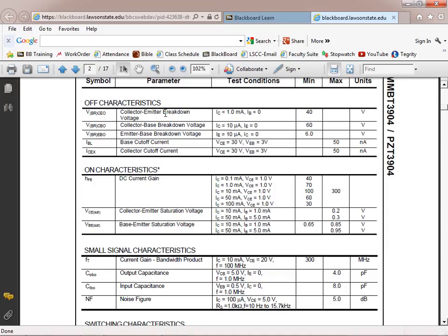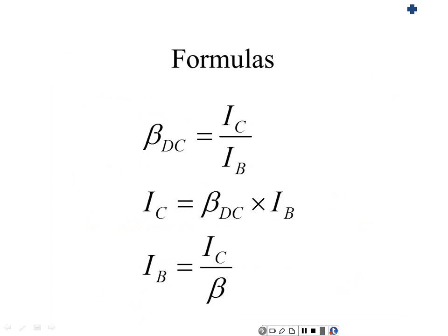And if we exceed the reverse bias voltage on the base to emitter, 6 volts. So that means if I let more than 6 volts reverse bias get on my base to emitter, then it's going to break over and you're going to mess the transistor up. The problem with transistors is they can open, they could become leaky, they could short, they could do all types of things. Transistors do all types of things when they go bad. And how do we check them normally? With an ohmmeter.